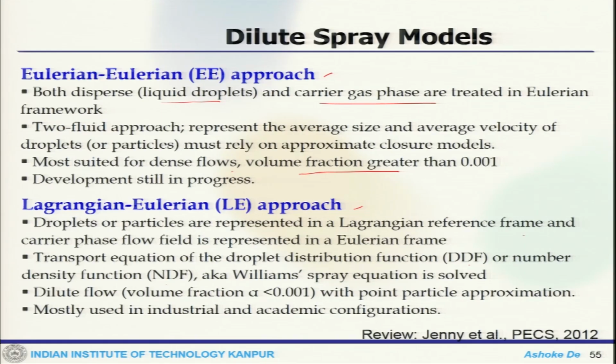It is quite well known that interaction with the ambient flow can significantly alter the collision characteristics in particle laden or droplet laden flow, and the effective restitution coefficient is a function of the particle or droplet Stokes number. These effects are incorporated in the Lagrangian approach. Also, from a numerical standpoint, it minimizes the numerical diffusion in the dispersed phase.